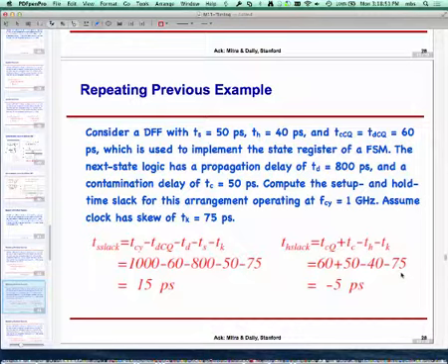So the effect of skew, in the worst case, depending upon where the skew goes, is that it reduces the margins you have, and that can cause violation. Part of the reason we leave the margin or the slack is to take into account that the delays through this clock network, by the time the clock reaches, are very hard to predict. They tend to be very complicated to analyze. And given that so much is riding on the speed and correctness of the chip, there are very fancy tools with very sophisticated algorithms whose sole purpose is to take your entire chip and do all this timing analysis for you.